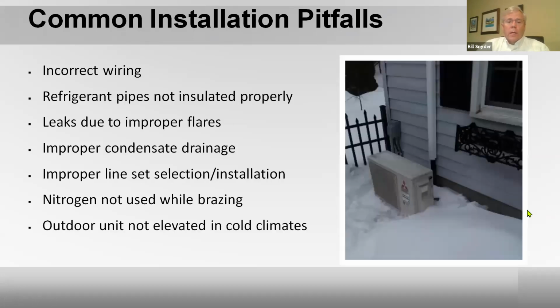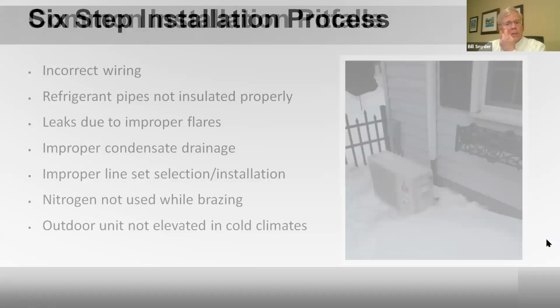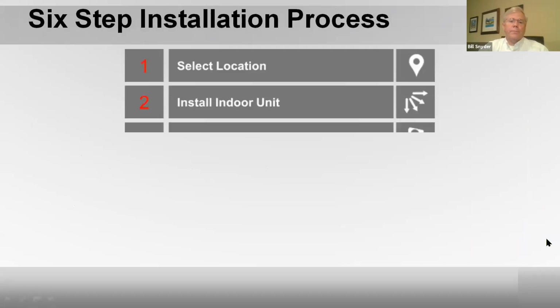Also, in our climates, we're in a cold climate, this unit should be elevated. If it's a cooling only unit in like a server room, you want to elevate it just to get it above the snow line. If it's a heat pump, when it goes into defrost, this will ice up and it'll break the unit or just fill up with snow and not work. So those are common problems.